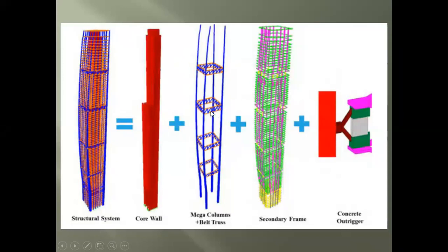So these outrigger truss belts will surround this core and will transmit the loads to the columns which are installed in the 4 parts. So mega columns, actually there are also intermediate columns which accept and transmit the loads, but mega columns means that the section of these columns is larger and the bearing capacity is also greater. They are located at the 4 edges of this building.